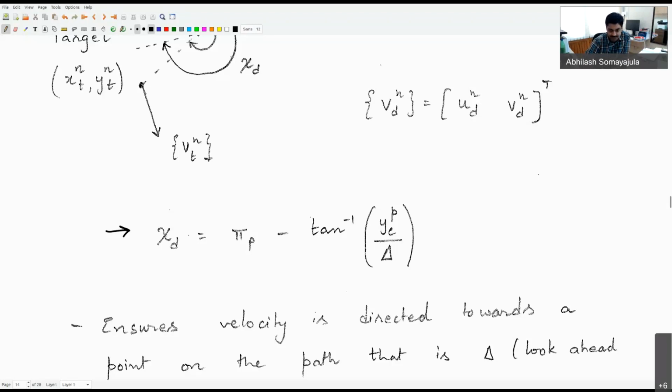Sir, when the ship has a velocity, will the course angle and heading angle be the same? No, need not be. Because they will differ by what is called the crab angle, which is the drift angle. Remember, we covered that in one of the beginning lectures in chapter 2, where the idea was that the ship may have an orientation this way, but the velocity vector may point this way. So in which case, definitely the two may not be the same. But if a ship is moving in a straight line, yes, the course angle and the heading angle will be the same.